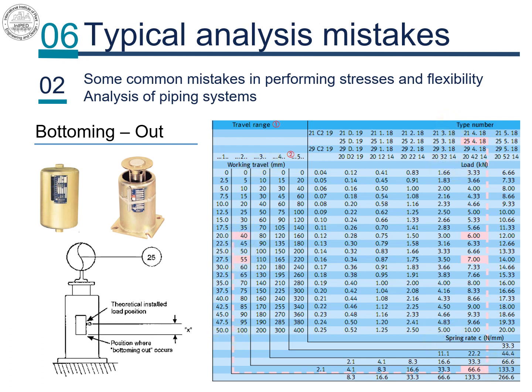The initial load, so-called cold or installation load, is set on the spring to be 6 kN. In other words, after removing spring locks, when the pipe is already sitting on the spring which has been factory precompressed, it will release a reaction force on the pipe of 6 kN. This load will, according to stress analysis, keep the forces on the piping system in equilibrium, and the spring will be in its theoretical installed position.